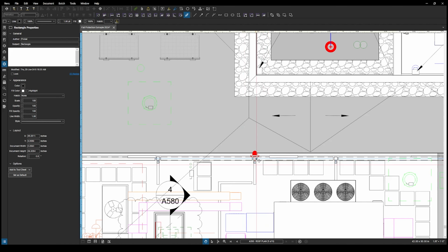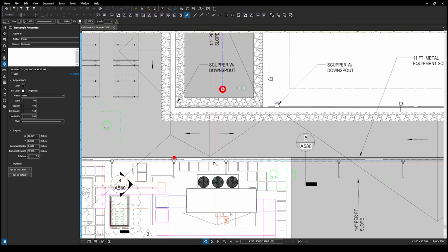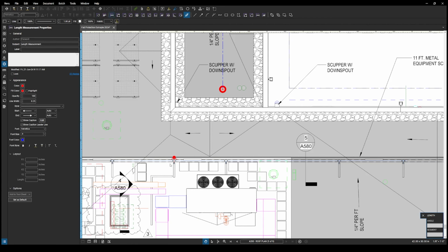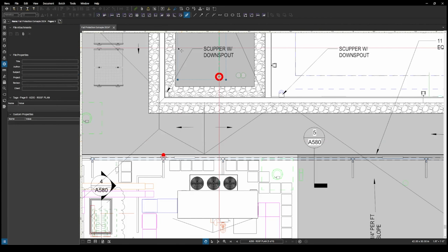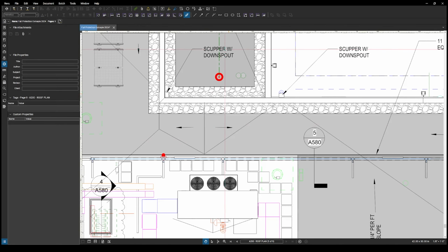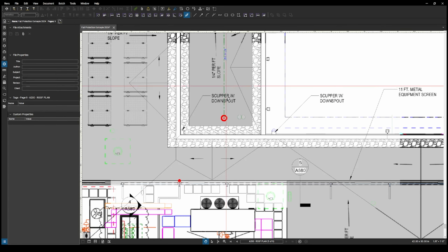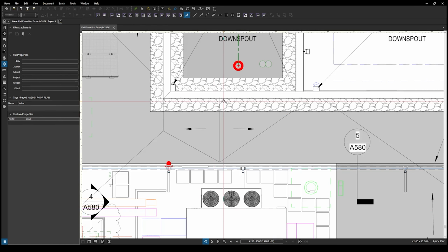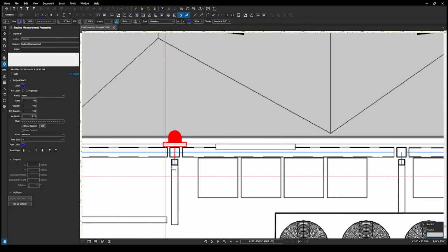And so we do that with wall anchors. So in this case, we have a screen wall over here with vertical posts that are typically set at like 14 feet. And that works out great actually. Like I was saying earlier, the maximum span we can have for anchors is 30 feet, but for a cable system, we don't have to be as much. So I'm going to start placing my wall anchors in at every single vertical post that would be usable for this.